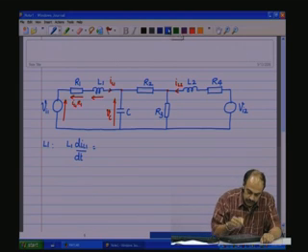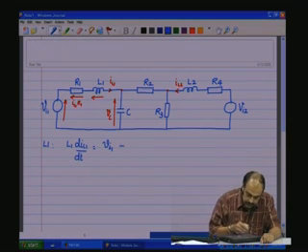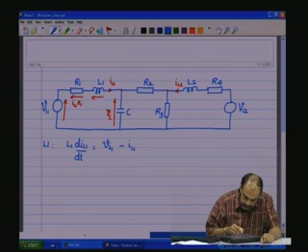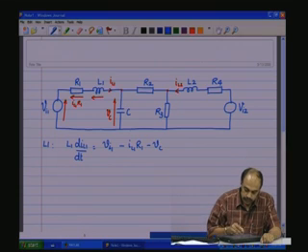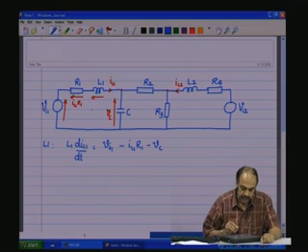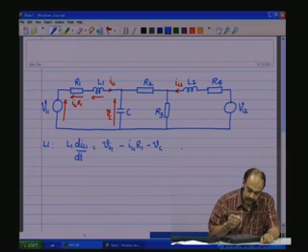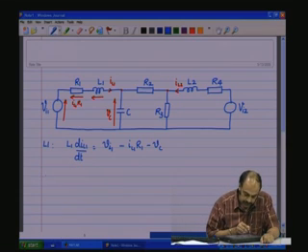So, now we have the equation which is very simple. We have VI1 minus IL1 R1 minus Vc should add up to the voltage across the inductor, such that the algebraic sum of the voltages in this loop is 0 by Kirchhoff's voltage law. So, this is our first equation, and now the second equation.